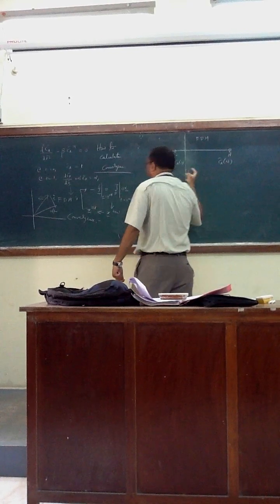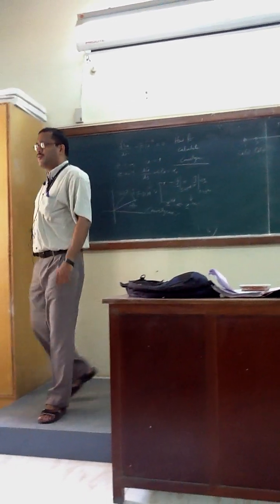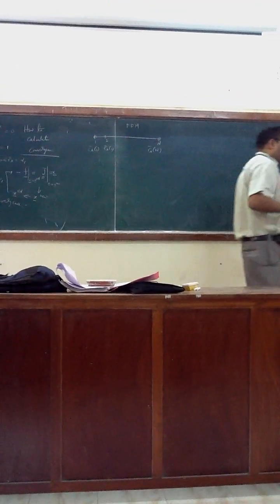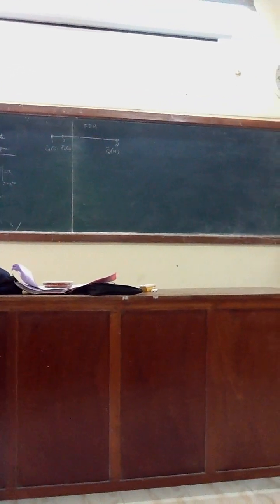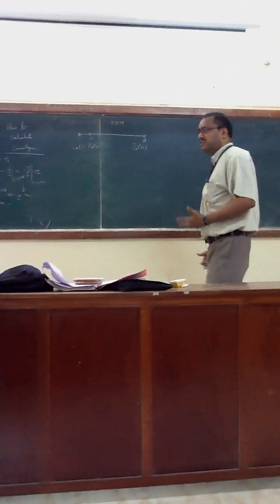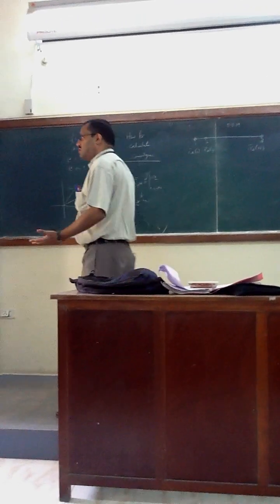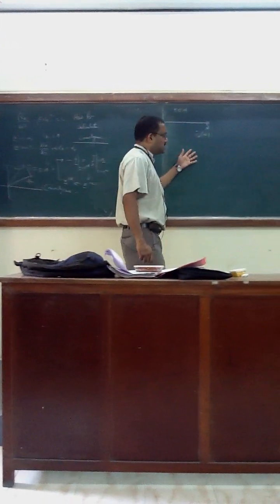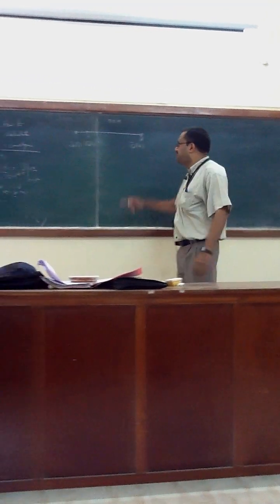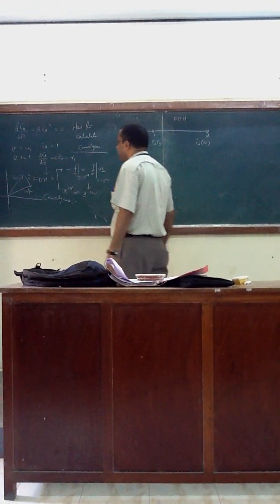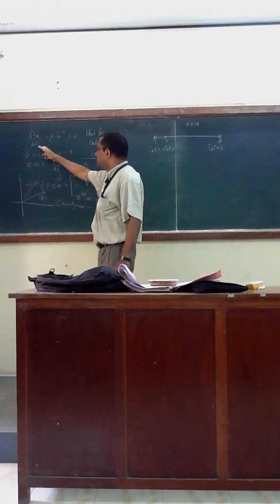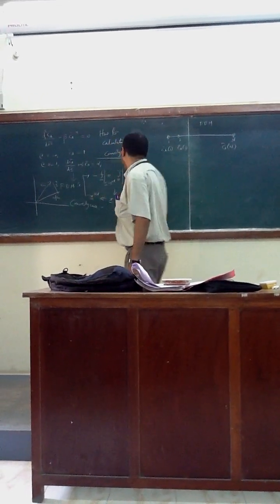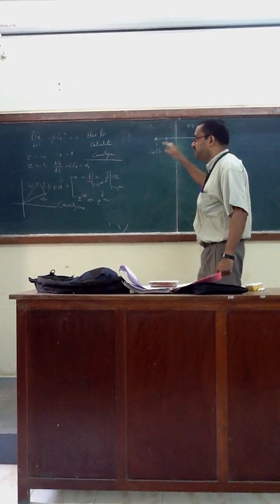In a computer program, these are called dimension variables. Eventually whatever you have learned, you have to do in the computer program, because these days, without a computer program, nothing goes, because you have to work on 1,000 differential equations, 1,000 algebraic equations. So there are n variables. Each variable represents each node. As I say, in the finite difference method, this differential equation should be written for each node, except the boundary nodes, where the boundary conditions are specified.